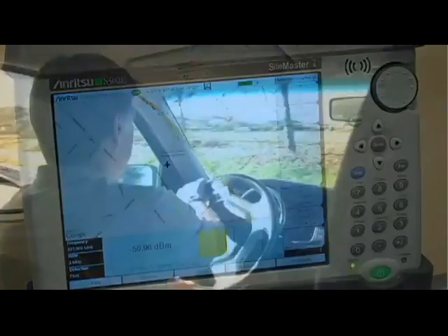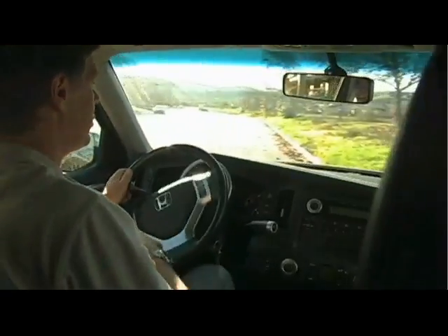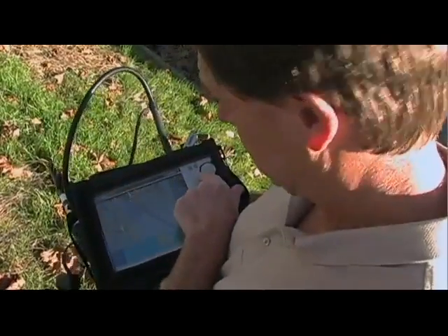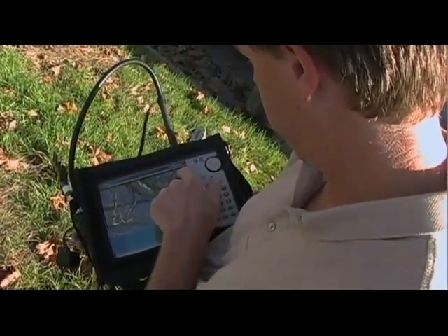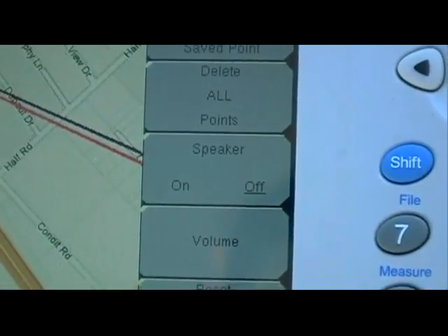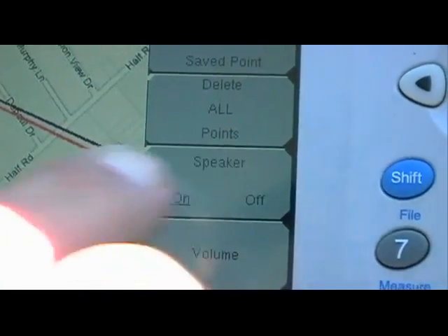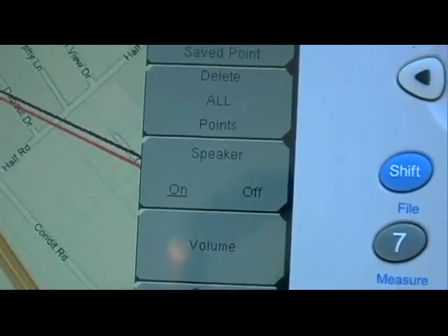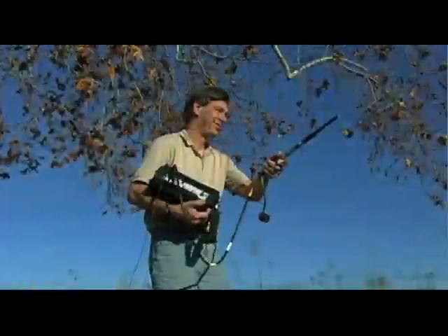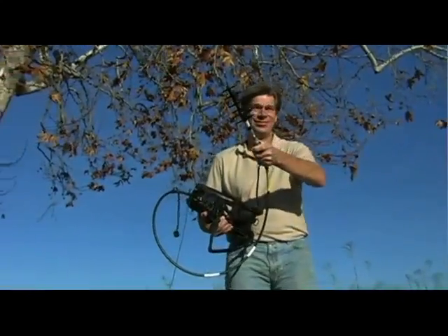After all of your equipment is ready and set up, you can now start interference mapping. Move to the needed location outside. The instrument will automatically set your position in reference with the on-screen map. In the Interference Mapping menu, pressing the Speaker soft key turns the sound option on or off. If on, a series of beeps helps find the direction of where the interfering signal is strongest.